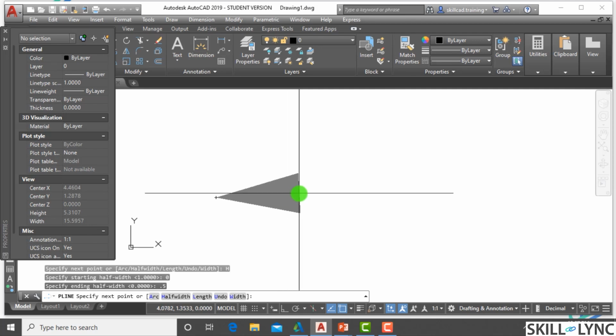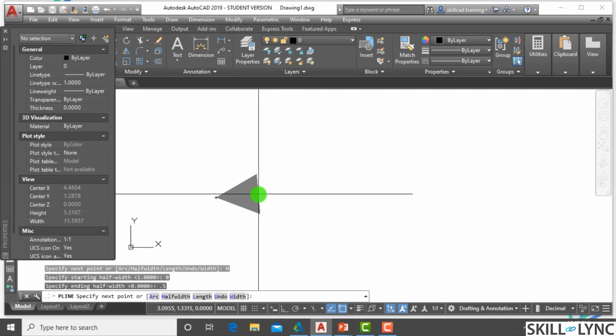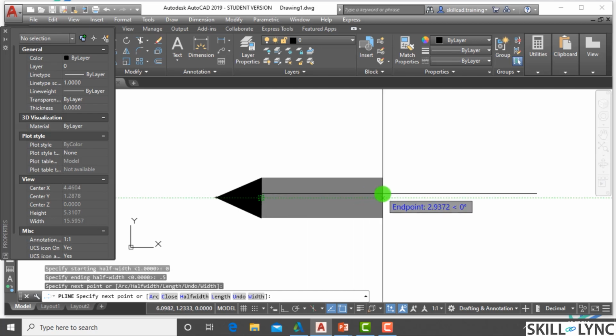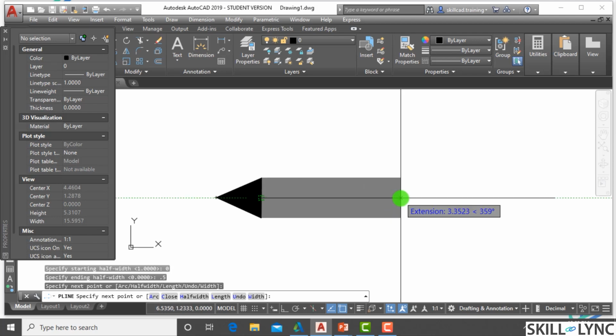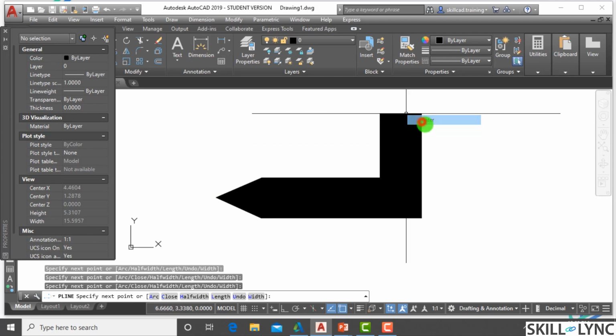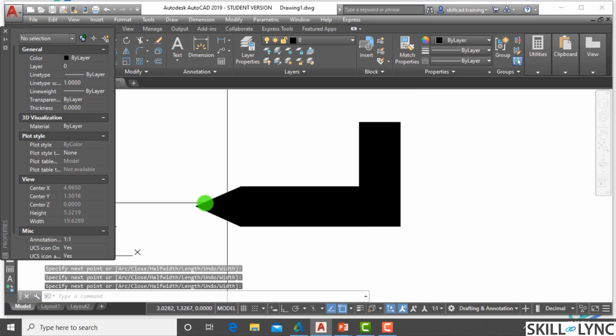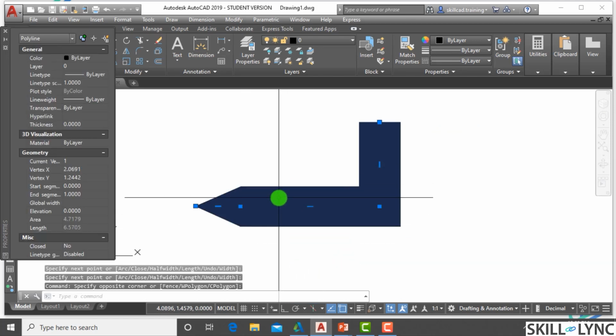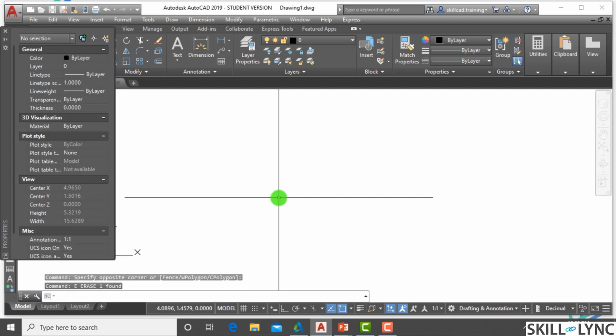So let's say I have an arrow and I am pushing it in a particular part. You click here, and from here onwards the width will be taken as whatever is at the end point. So now the width is 1 throughout. So you can have this kind of geometry, or wide geometry, with a polyline using the half width. And width is the same. If you go with the width, you need not give the half width.